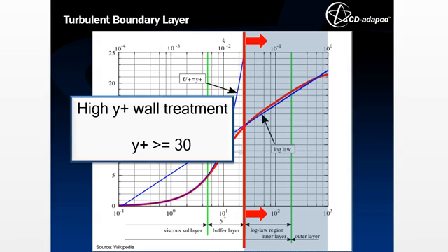The upper bound depends on the type of the simulation. While there have been successful applications in the marine and civil engineering sector with Y plus values as high as 500, a value of 100 is recommended as best practice for most applications and should not be exceeded without proper validation.